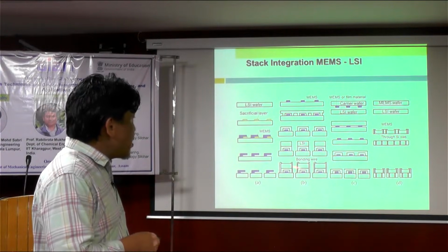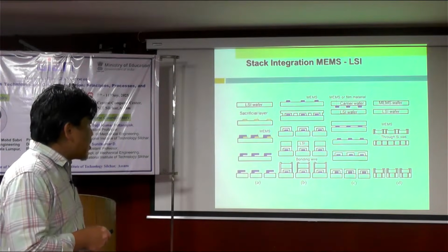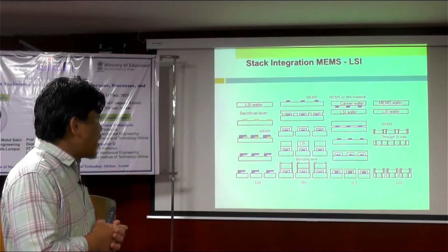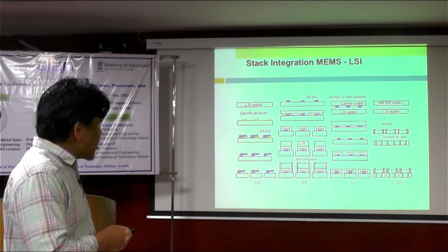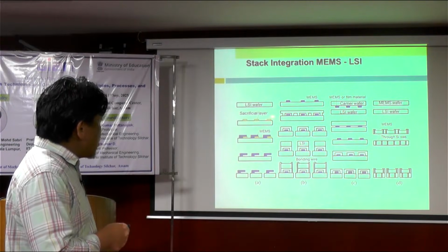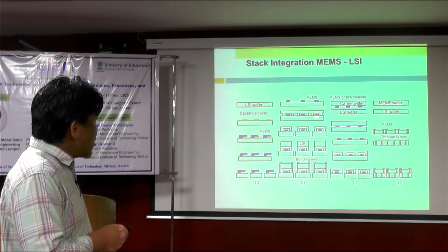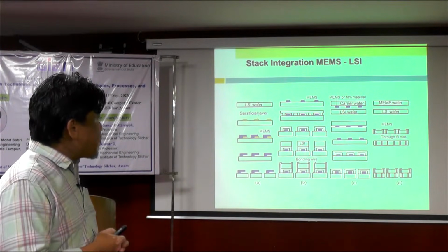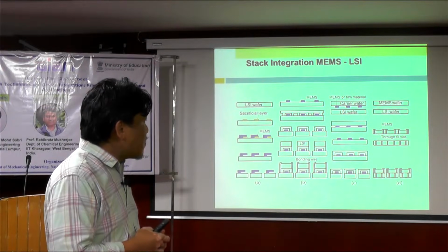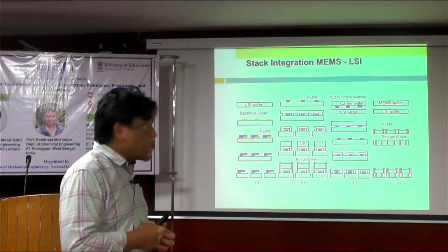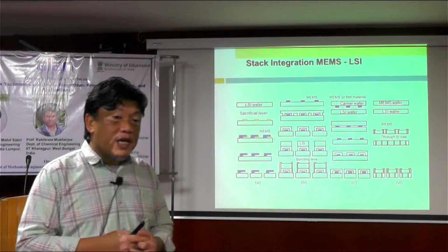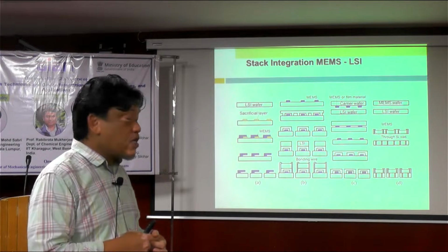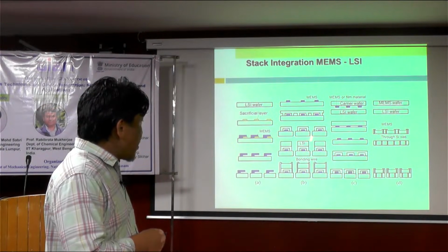So this might be an approach which nowadays makes things high performance of computing and high performance of devices. You see that the integration in a vertical manner saves a lot of space. Instead of going side by side, you just stack on top of it. But this process requires a lot of careful attention in terms of packaging, in terms of connecting the electrical circuitry, and in terms of reliability, in the bonding of wafer silicon, for example. It is quite difficult.